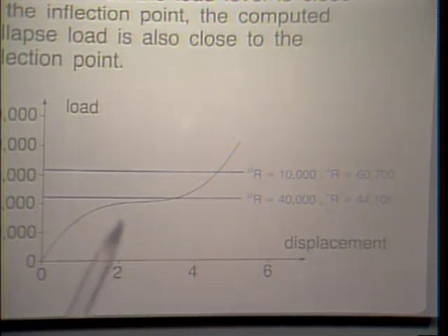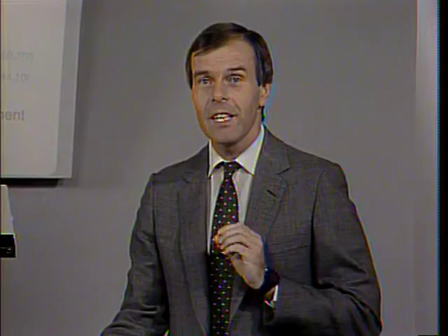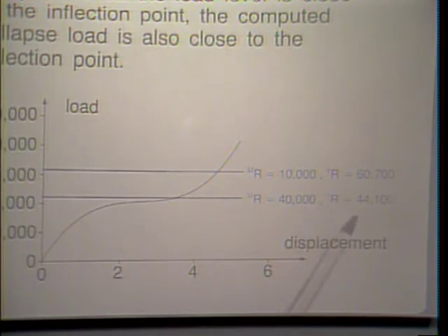So here we learn something more from this example, namely that in the linearized buckling analysis, we may predict a collapse load, but there may not actually be a collapse load in the structural response corresponding to a singular stiffness matrix. Whether you really want to accept this here as a collapse load depends on your design criteria.